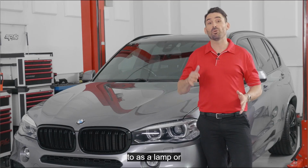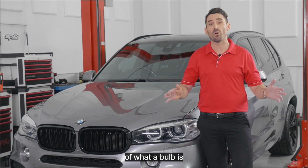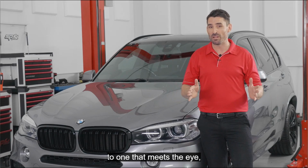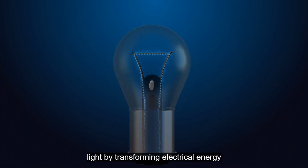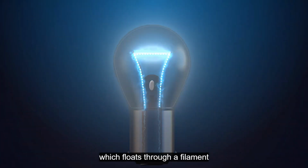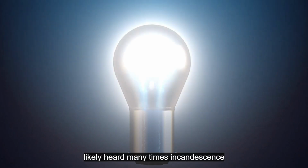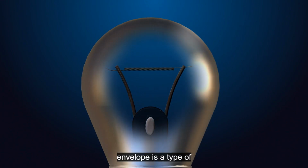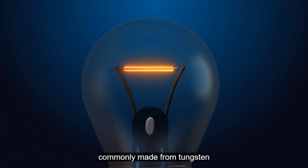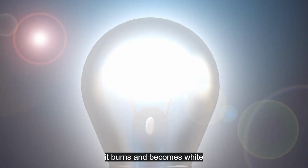At times referred to as a lamp or light globe, we most likely have a basic understanding of what a bulb is, but there is more to one than meets the eye. Put simply, a bulb produces light by transforming electrical energy, which flows through a filament, into heat energy. This process can be described by a word you have most likely heard many times: incandescence. The filament, which is enclosed within a glass envelope, is a type of resistance wire that is commonly made from tungsten. As current flows through the tungsten filament, it burns and becomes white hot.